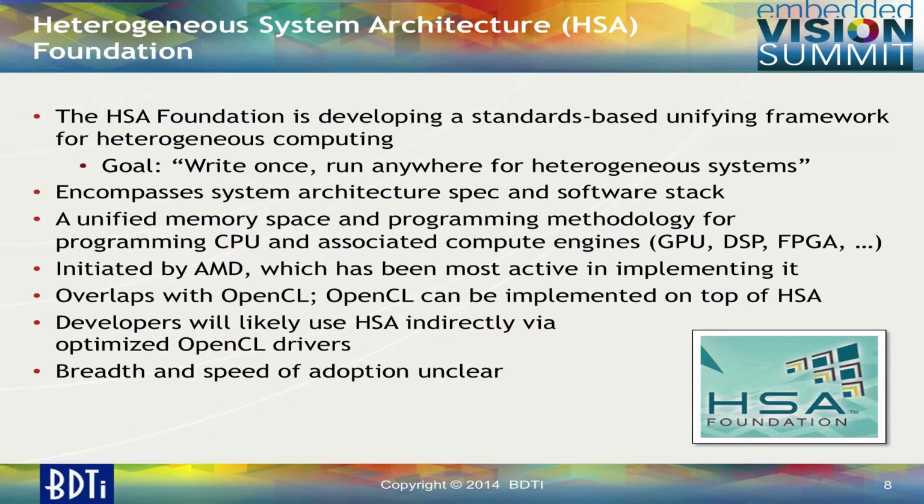As you probably know, a common problem in processor-coprocessor architectures is that, yes, the coprocessor runs a piece of the workload much faster, but the overhead associated with moving the data from the main processor to the coprocessor and then back as they share the workload, if you're not careful or if you're unlucky, can negate the gain that you hope to get by running a certain portion of the code faster in the coprocessor.